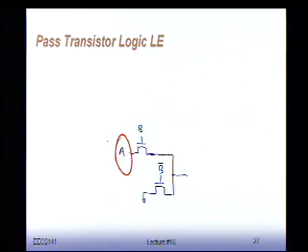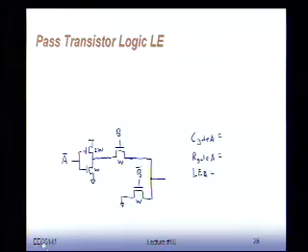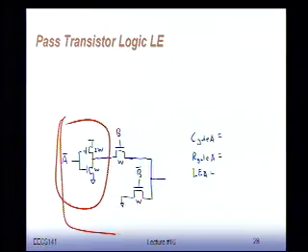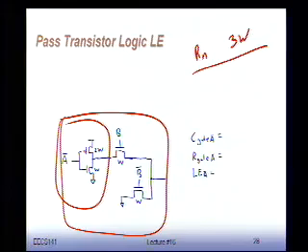So if you want to do this correctly, you have to extend the question a little bit. The more realistic situation would be something like this, where A comes out of an inverter, a restorer, and then we feed it into the network, and we have a B and B-bar network. Because now, for my overall computation, remember, the inverter has a resistance equal to Rn, and a capacitor which is 3 times W. That's the reference case. So we look at the gate capacitor that we see for A bar. Well, the gate capacitor is the same as an inverter, 3W.